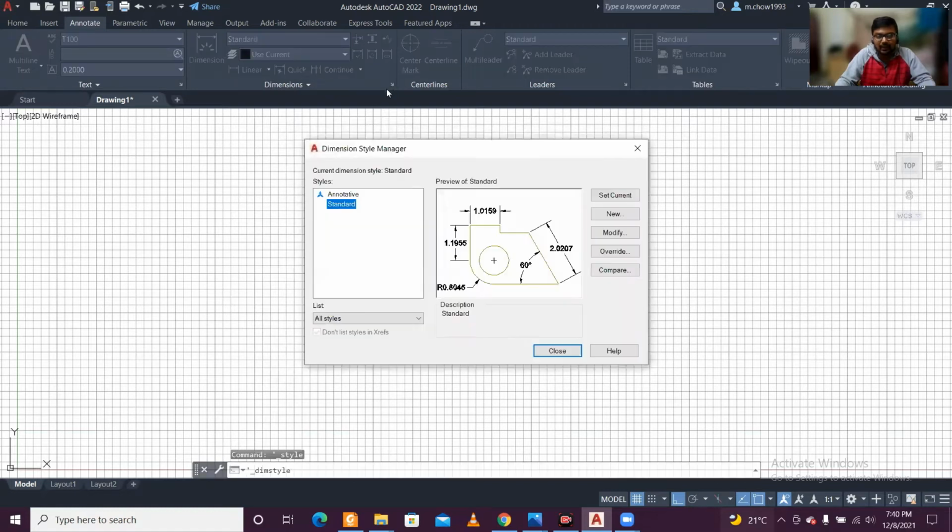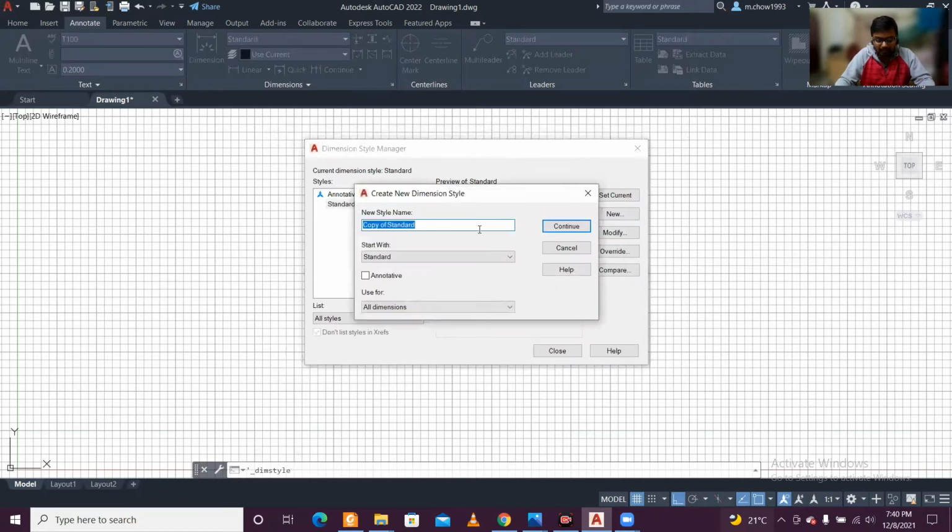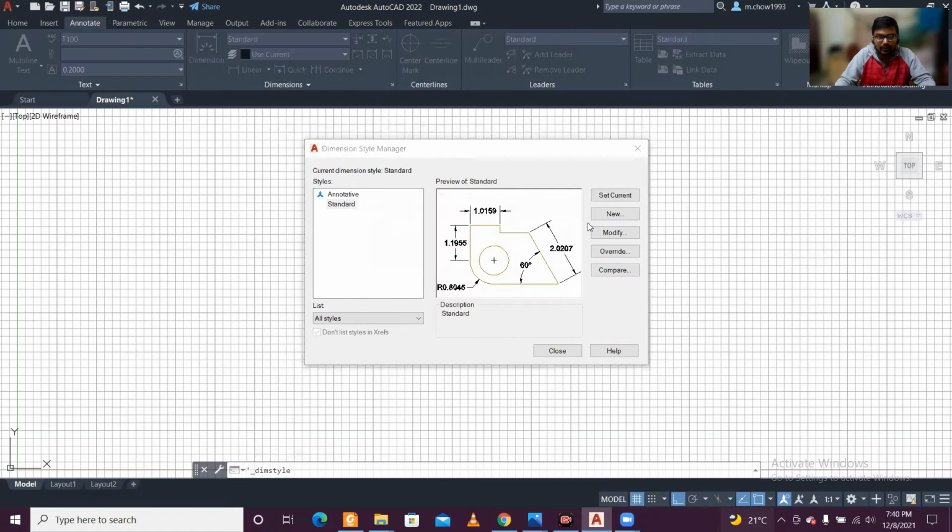The dimension settings are also very important because this arrow should be visible on my final printed A4 sheet, which will be scaled by a factor of 100, 75, 125, 150, whatever, depending on what I'm going to draft in that particular zone. So for the dimension settings, I'll go for a new style, and I'll name it D100. It helps me to remember that I'm assuming a scale of 100. So I'll just continue with this.